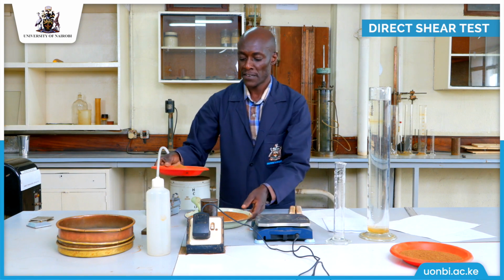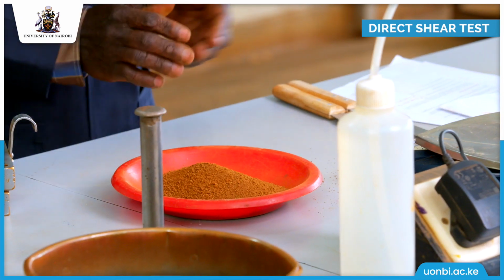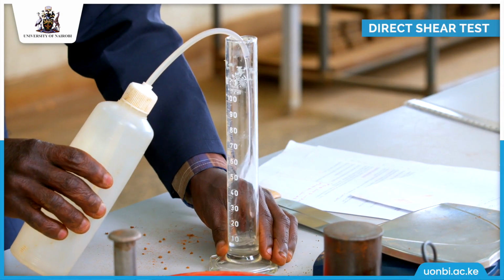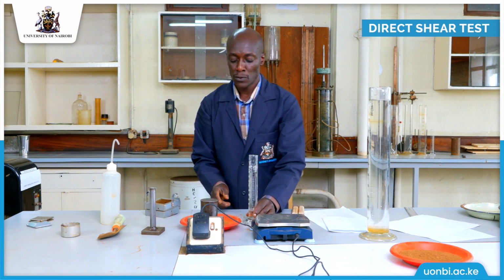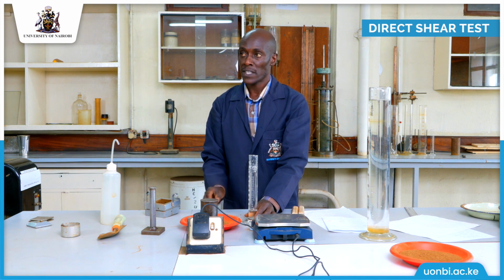This is my 210.7 grams. The next thing that I'll do is to measure 18 milliliters of water. So I'm going to mix this soil sample with this water.